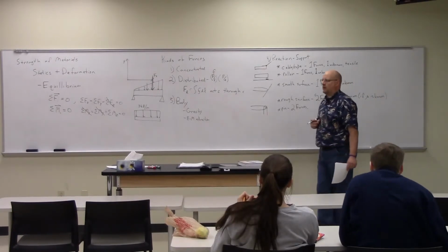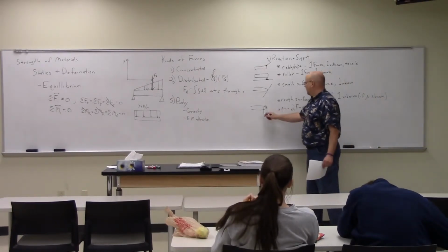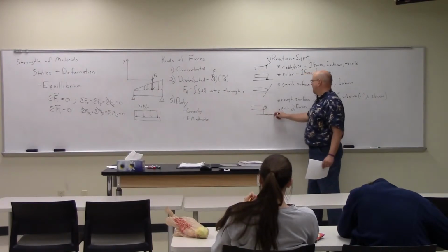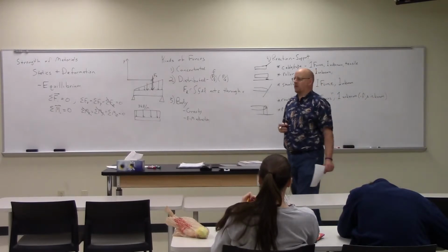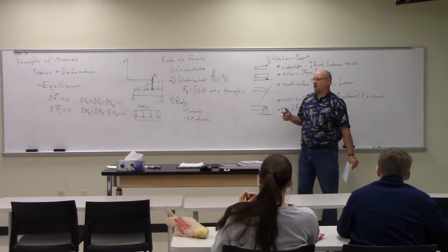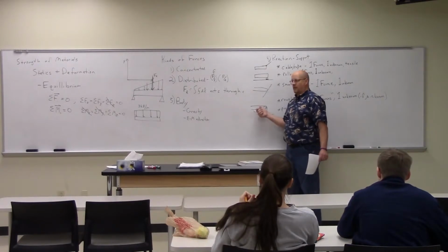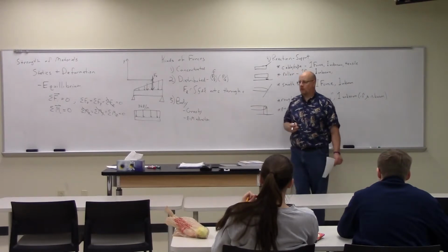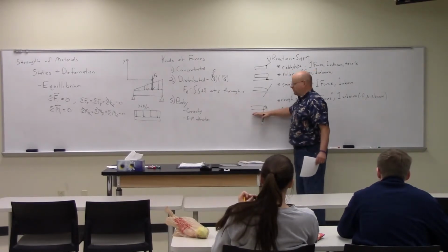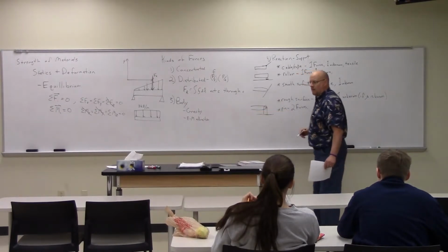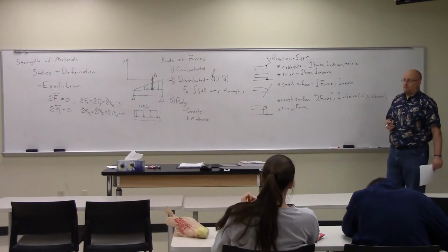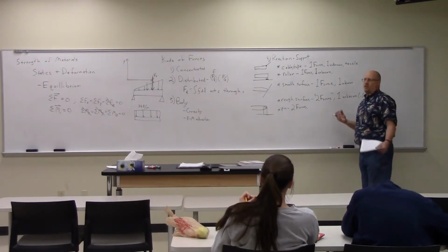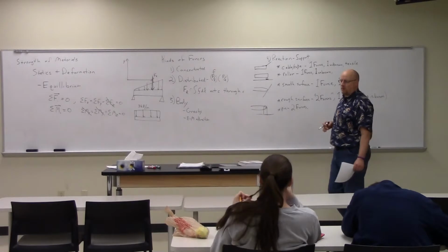I'm not sure I understand what you mean. So in other words, if this was the ground? If the pin was extruded from, say, a molded-in pin, it's not rigid to the other one. So one can still exert two forces on this one. There can still be two reaction forces, and it doesn't matter whether this is attached to the ground or not. As long as it's free to move about one of the two, then you have rotational freedom. So it doesn't have to be rotational in both of them. And generally it won't be. Generally, one of them will probably be fixed.